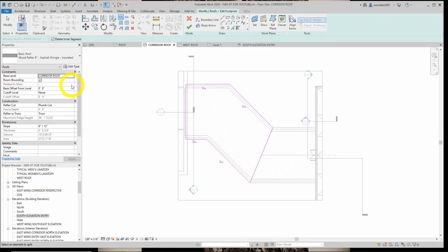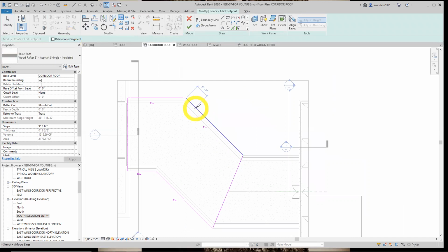Going into page 365 towards the end of the chapter, I'm going to say, where do I want my first point? So it's going to cut out the middle, or not deselect, my bad. We want to leave it. So what I did on here that seemed to work for me, I just hovered to an even integer 4. Hovered there, it looked good. I selected. Did the same on this side. Just use the power of Revit to go to even integers, inches here. And escaped twice. Select the middle line.